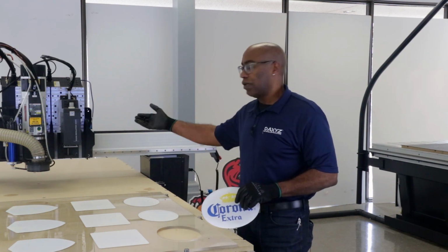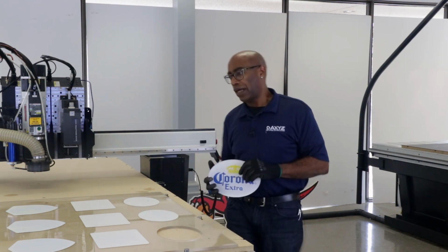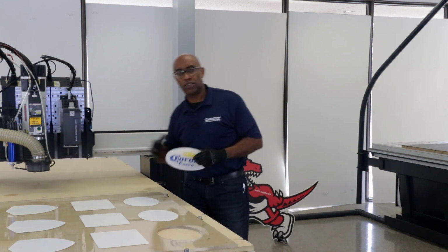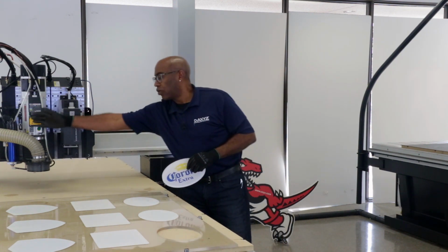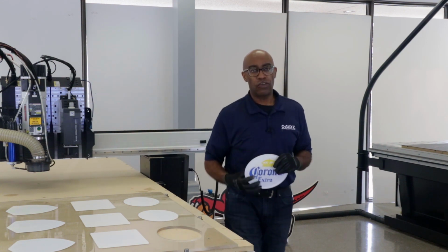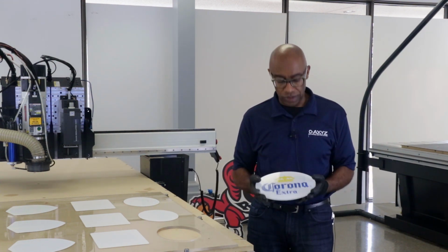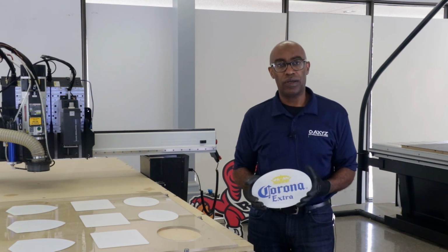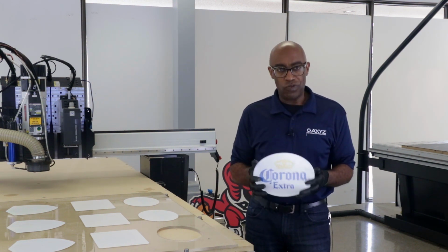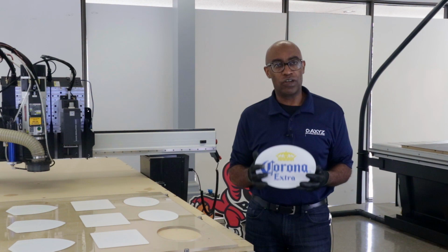Again, because of the way our dust collection is set up, the use of our bellows to give you a nice good seal in terms of dust collection, and the cold air gun moving the chips around, it allows you to evacuate the chips better, which will basically help in terms of the cut process and the edge quality that you will produce. Again, on this Infinite, we've just processed 1/2 inch acrylic using our AVS system.